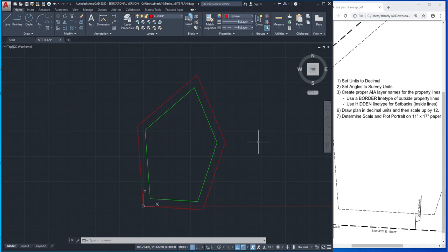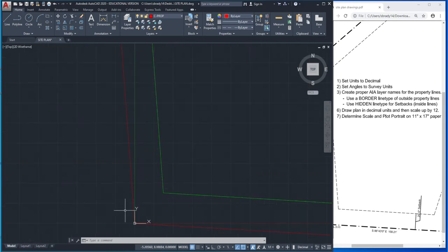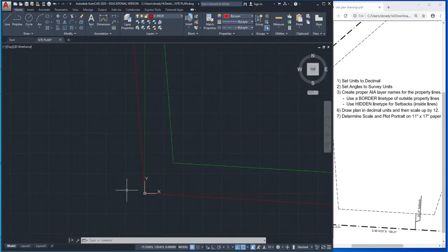So sometimes I get assignments where I know that the thought was there. I know that you knew how to draw it, how to put the layers, how to print it, but you struggled with the scale and it was 4 times the size it needed to be, right? Because you thought, oh, I scaled it, I can't visually see that I scaled it, okay? And it is tricky. One little piece of advice to make sure you recognize if you've scaled something correctly is you can draw a line.